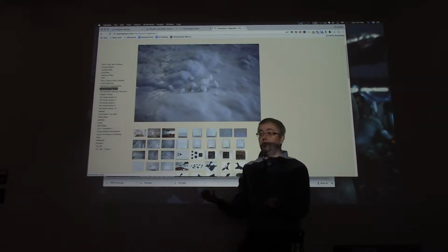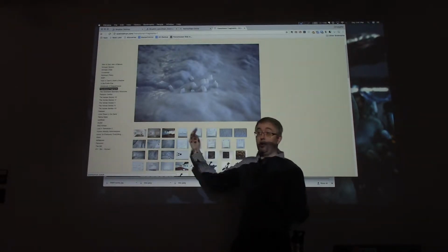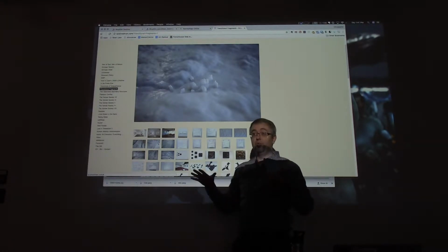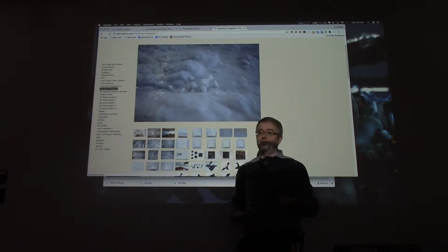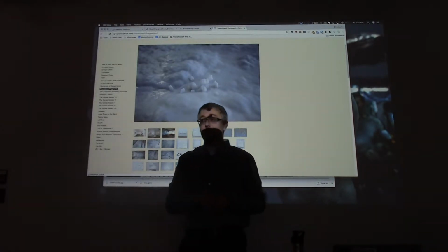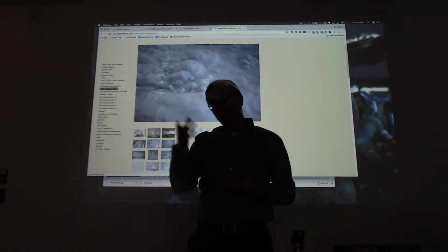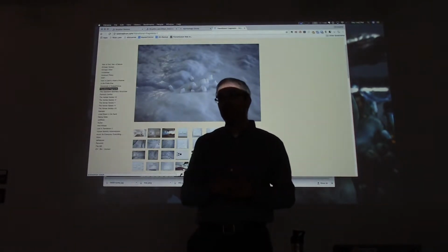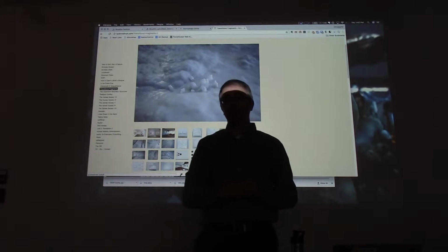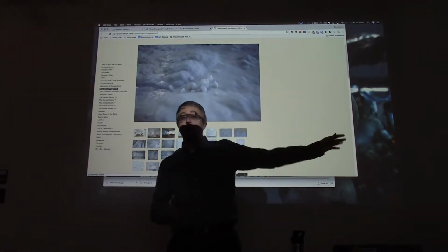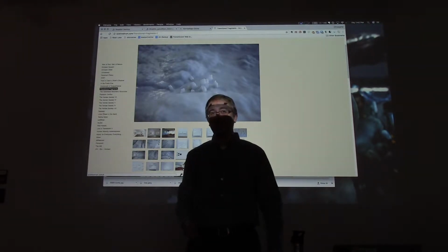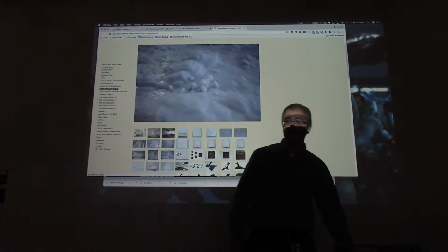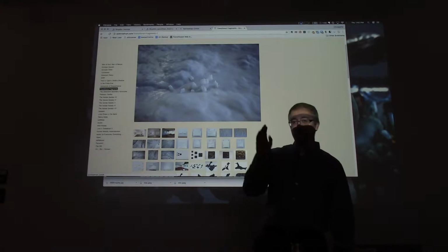And so either you screw it from below and then hope your tip never hits any of the screws, or you leave it in a frame, carve all the stuff away, and then the last thing you do is cut it out. It's a good question. Make it like a temporary frame for that size, right? Yeah. That's another tactic, and we'll talk about some of those because I don't know what engineering uses, so I'm going to have to go over and find out what they're going to use for their waste board and all of these pieces. But yeah, these are important questions.